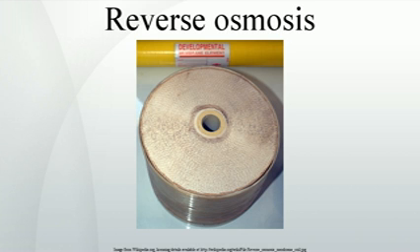Energy recovery. Energy recovery can reduce energy consumption by 50% or more. Much of the high-pressure pump input energy can be recovered from the concentrate flow, and the increasing efficiency of energy recovery devices has greatly reduced the energy needs of reverse osmosis desalination. Devices used, in order of invention, are turbine or Pelton wheel, a water turbine driven by the concentrate flow, connected to the high-pressure pump drive shaft to provide part of its input power.